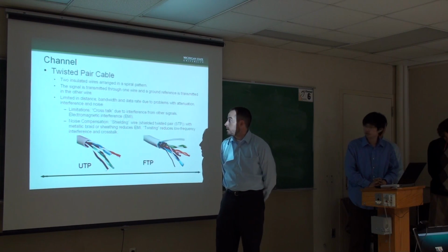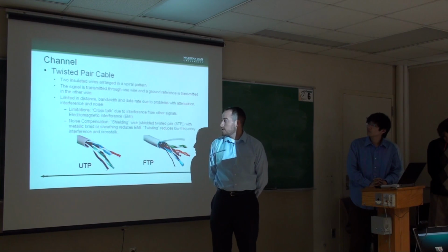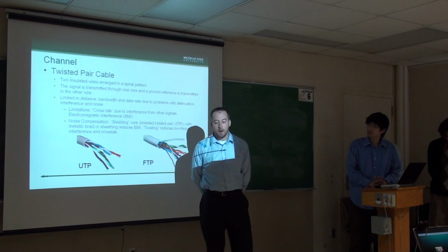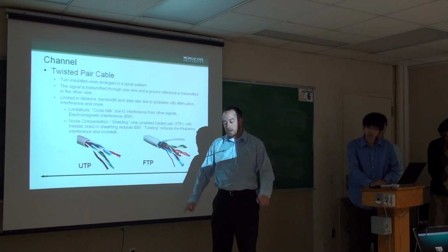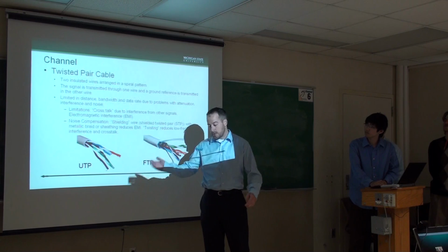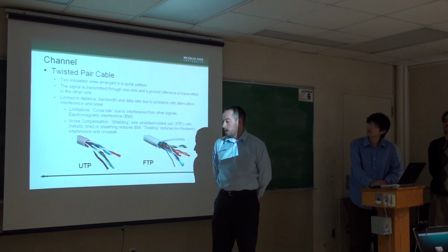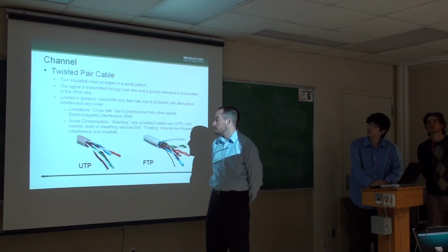One is wired to our output from the transmitter, and the other would be wired through ground. The ground should not be tied together from the receiver and the transmitter to avoid any common mode noise.